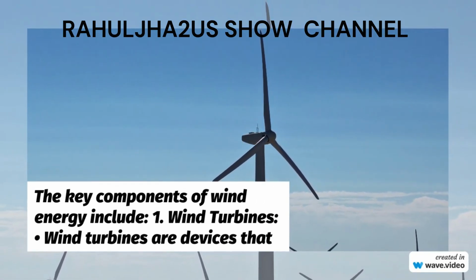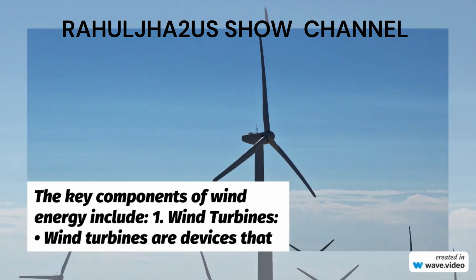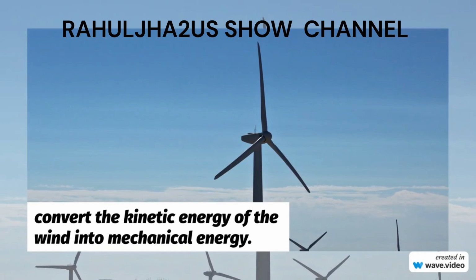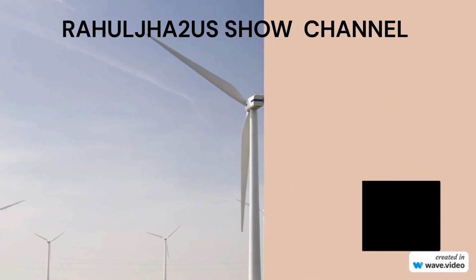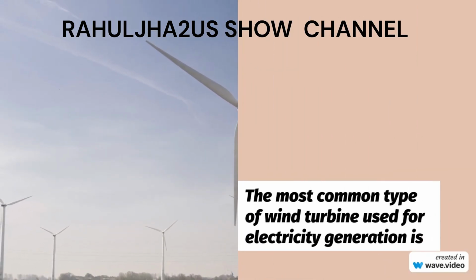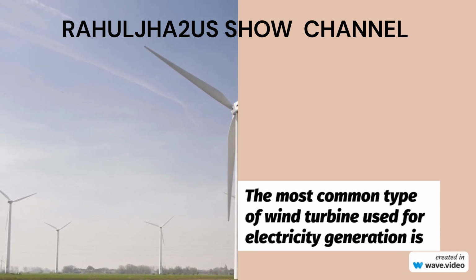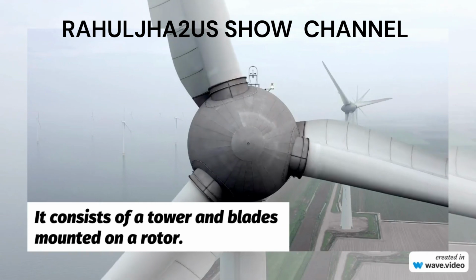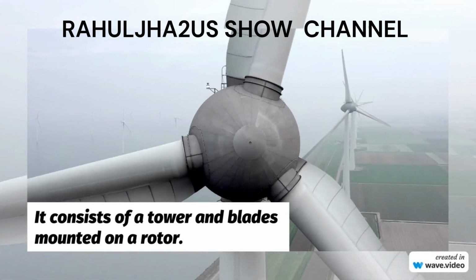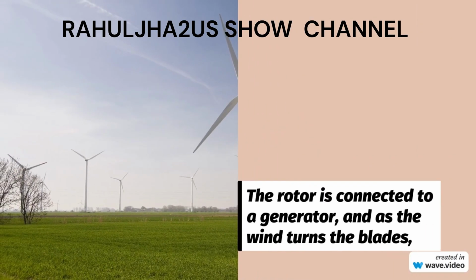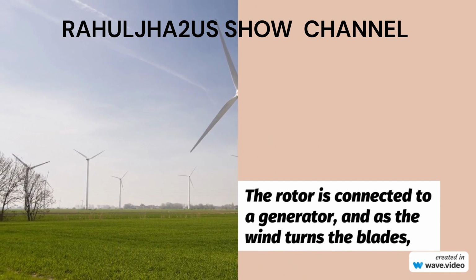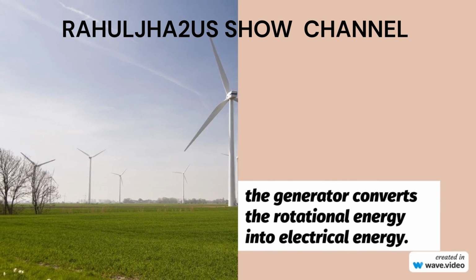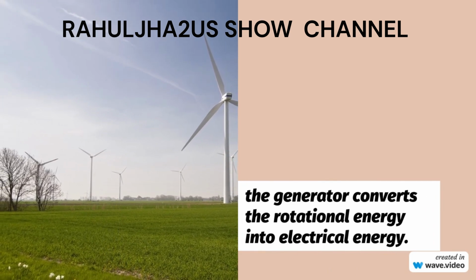The key components of wind energy include wind turbines. Wind turbines are devices that convert the kinetic energy of the wind into mechanical energy. The most common type of wind turbine used for electricity generation is the horizontal axis wind turbine, HAWT. It consists of a tower and blades mounted on a rotor. The rotor is connected to a generator, and as the wind turns the blades, the generator converts the rotational energy into electrical energy.